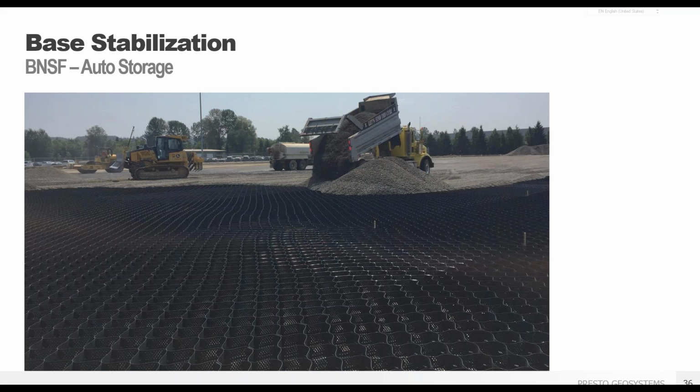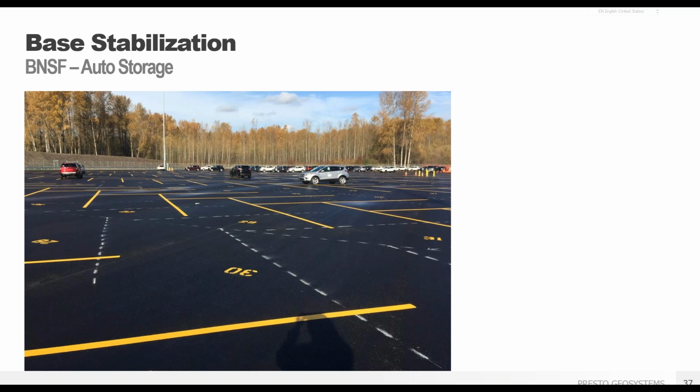Here we see the dump trucks just back up to the GeoWeb, dumping the infill material, and then it's spread with a bulldozer. The material supports loading immediately after filling, no cure time needed, and no special weather requirements. Again, serving as its own site access road for construction. And here's the finished surface.